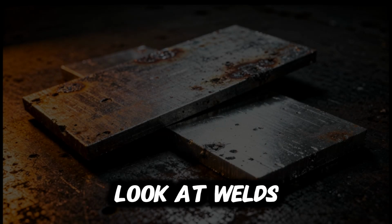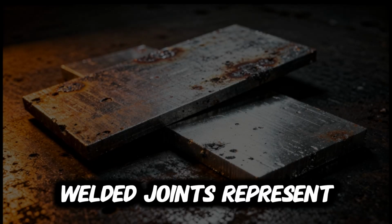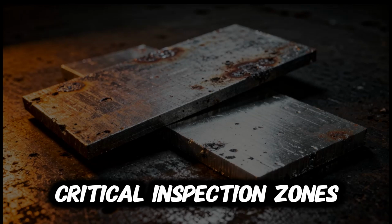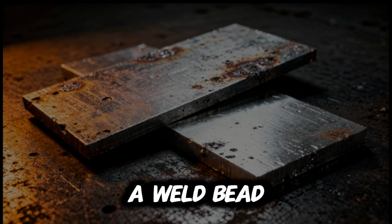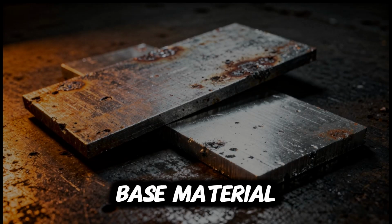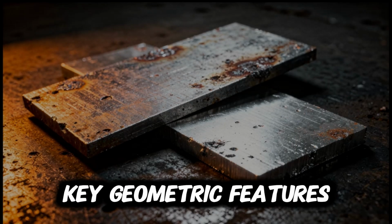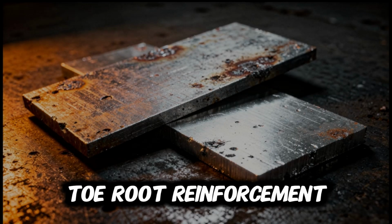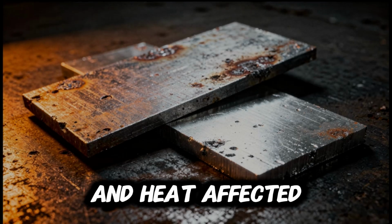And when we look at welds, what terminology matters most? Welded joints represent critical inspection zones where visual testing is most frequently applied. A weld bead is the visible deposit of filler metal fused to the base material during the welding process. Key geometric features include weld face, toe, root, reinforcement, and heat-affected zone.